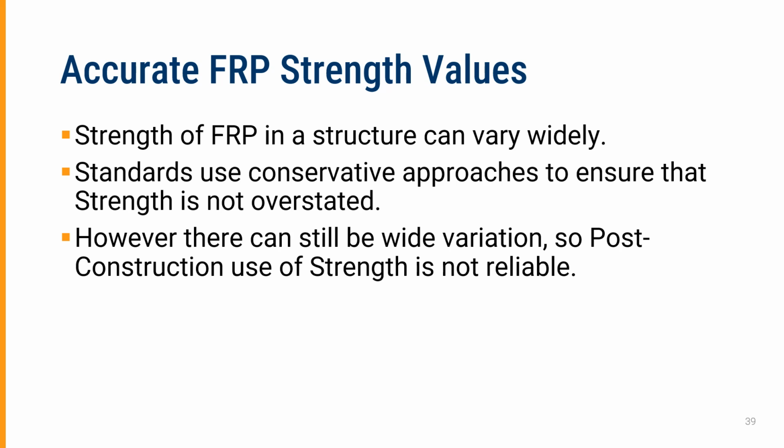Accurate FRP strength values are sometimes a little elusive. The strength of FRP in a structure can vary widely. The standards use conservative approaches that make sure that the strength is not overstated. However, there can still be pretty wide variation. So post-construction use of design strength or of original strength is not always reliable.